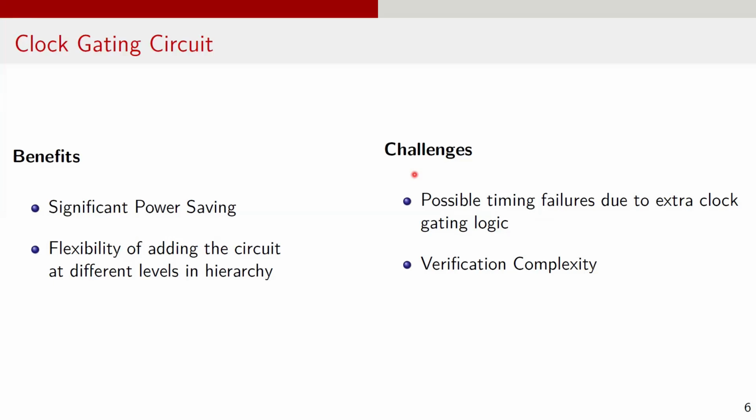However, there are a few considerations to keep in mind when incorporating clock gating circuits in a design. Implementing a clock gating circuit adds extra logic, which can affect the overall timing of the circuit. Therefore, extra caution is needed to avoid timing violations. Verification engineers must develop a thorough verification plan for clock gated designs, as improper implementation of gating can result in functional failures or reduction in performance.